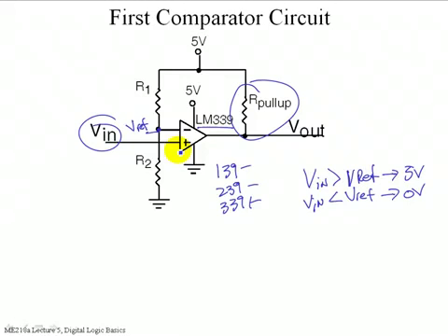Well, actually, the bit about the terminals having a very high gain is not one of the golden rules that I gave you. It's one of the requirements that leads to a golden rule. It leads to the golden rule that those two inputs are going to be at the same potential. But there's a requirement that was forgotten there. Yes, it's only true that the two inputs are at the same potential if it is in negative feedback, and it has infinite gain. That combination is what drives those two voltages to be exactly the same. So what about the input current?